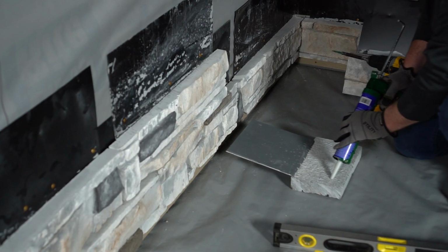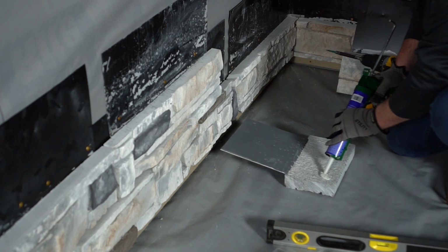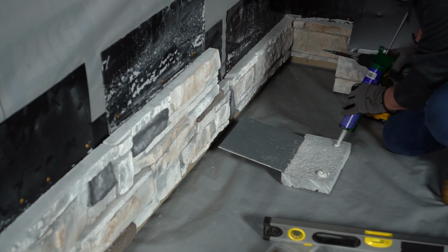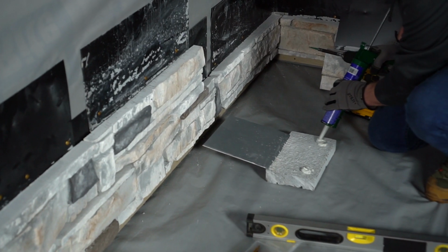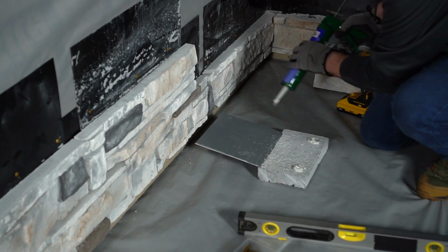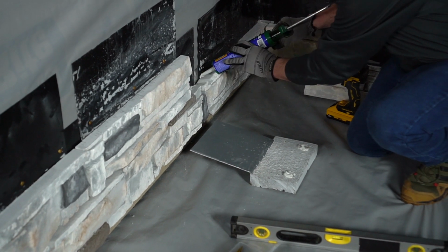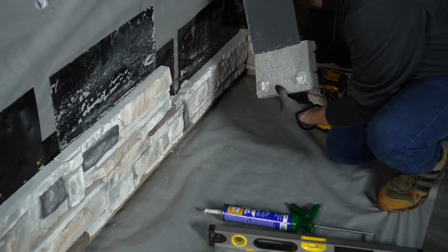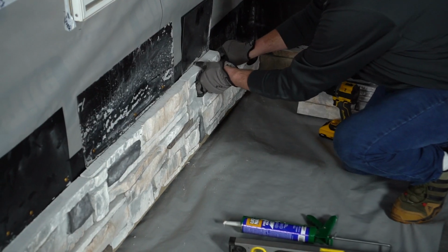When shorter panels are installed and no fasteners can be driven into a stud, supplemental gluing, as used on the initial course of stones, should be applied to the base of the backside of the panel and pressed into the aluminum flashing of a panel that is fastened to at least 1 stud. Additionally, apply a 1/4 inch thick dash line of adhesive along the top of the stone to the piece that it will be set on, leaving 2-inch spaces between dashes to allow water to escape.